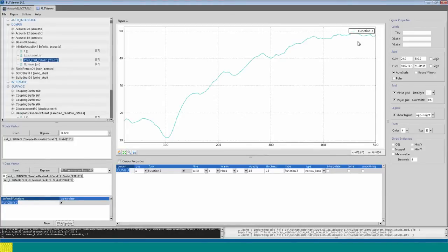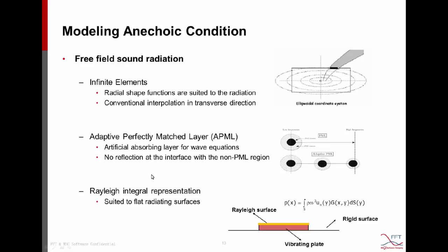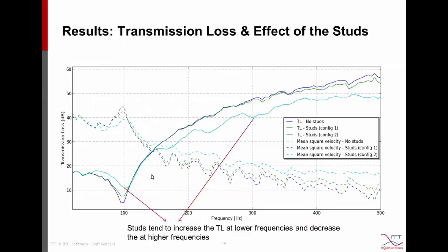And then, while in this demo model we didn't go to higher frequencies, which could be done by finite element modeling, in higher frequencies we will have some coincidence between the acoustic wavelength and the structure wavelength, and that will bring the curve down at the frequency that is called the critical frequency, and then it will go up. But we will see that behavior in the case studies later on. Now, let's come back to the presentation.